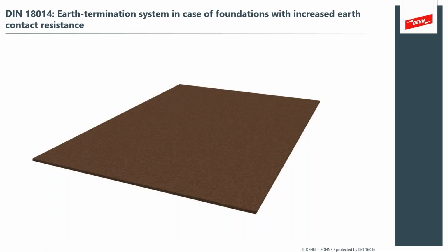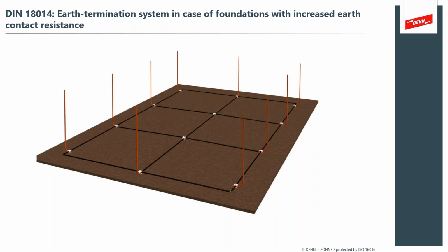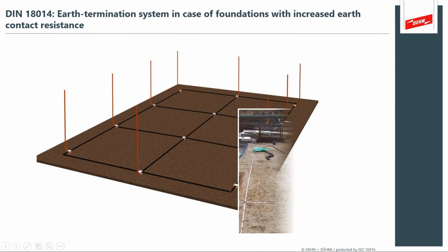I've got a series of illustrations that walk through what this should look like when you're doing an earth electrode system. You have your buried dirt and you're ready to start preparing this ring with your vertical risers. See these red vertical risers become connections to the rest of the building steel.